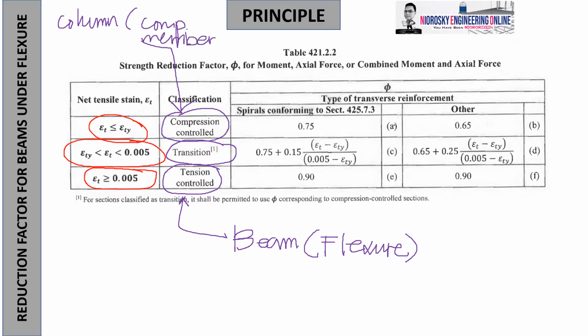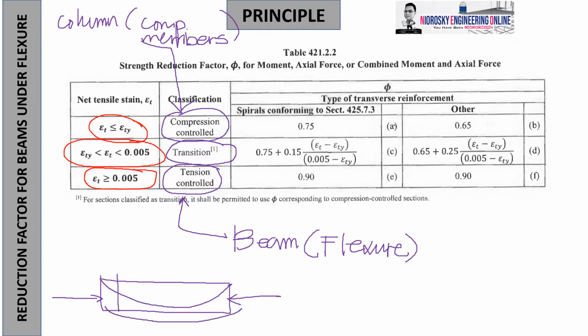Usually, the beam is known to be under flexure because the loads are gravity, so it will deflect towards the Earth, and therefore there will be some deflection going on. While a column, subjected to gravitational load, will compress the member, so what happens is compression. Usually that is what happens. But our beam may take on column-like action when the axial force is significant. Instead of only deflecting, there will also be a large compression value. This delta is different from the delta for deflection.